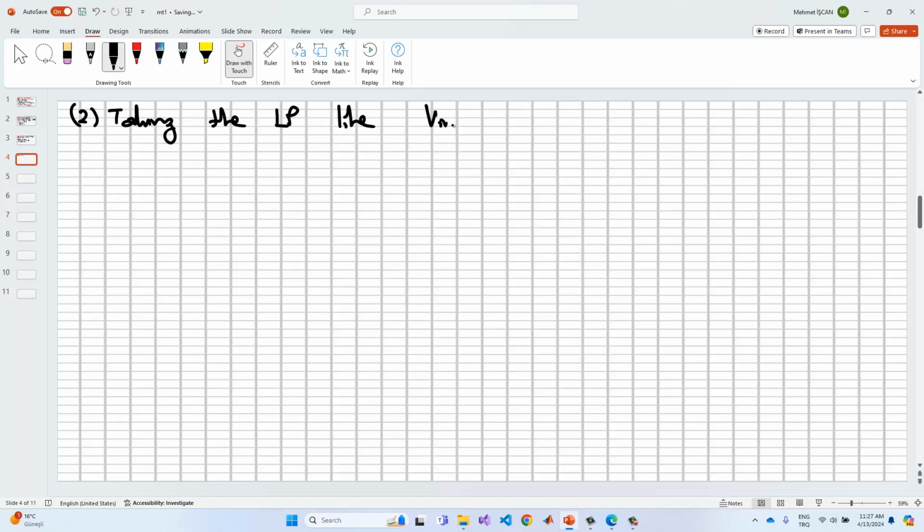Like V in is the unit step, which means that we have 1 divided by S in here, because we have the Laplace transformation of the unit step signal, 1 divided by S. Okay? And so we can write that 1 divided by S must be equal to RC S V out S, because we have the differentiation operation in here.